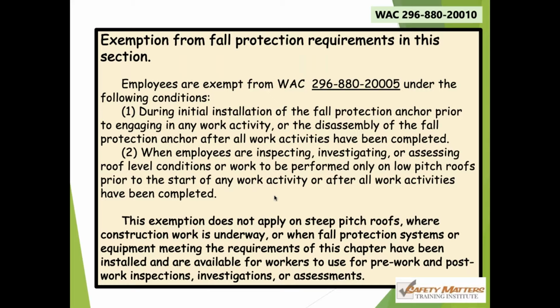Examples the department will not recognize as inspecting or estimating are going to include delivering, staging, or storing materials on your rooftop, and persons estimating or inspecting on roofs that would be considered the hazardous slope. Okay, so any steep pitch roofs, steep pitch is anything above 4 and 12. You don't get these exemptions. You have to be protected.